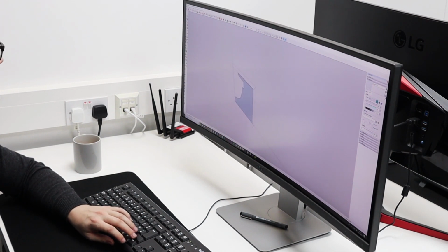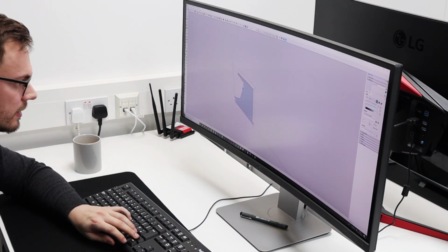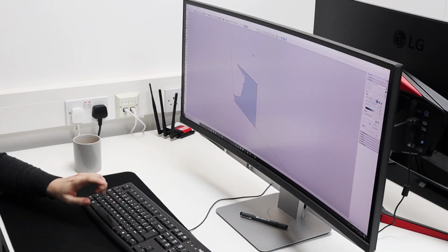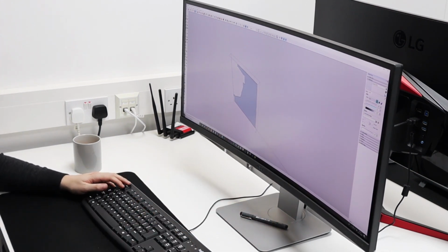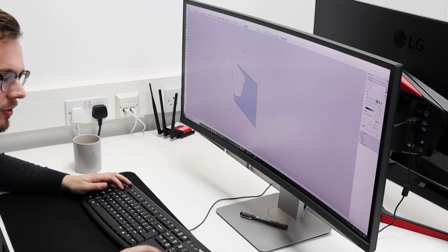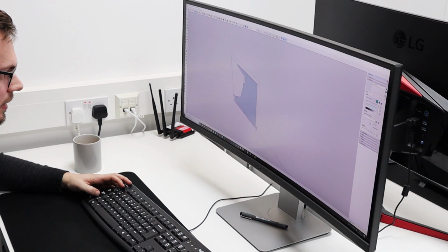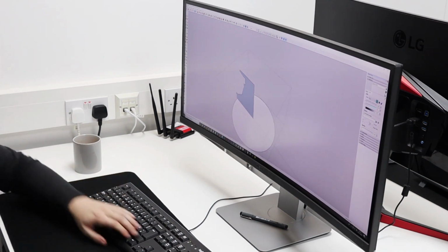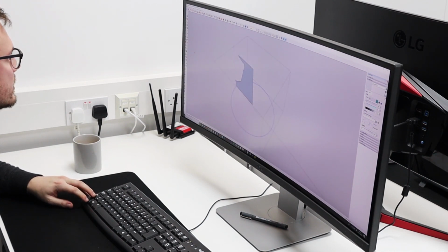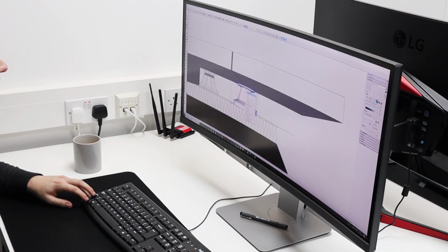These are normally circular. Just to give a circle more edges, when you've just clicked on the tool, you've got sides down here, I'll type 60, take the face off that, select the circle's edge, and there's your pedestal.